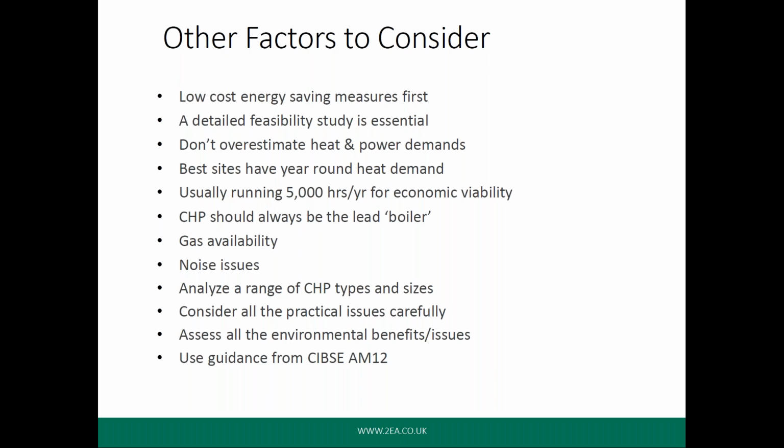Secondly, gas pressure can be an issue with combined heat and power units for a couple of reasons. The obvious one is, is there enough gas pressure on site? Unfortunately, there is not a standard pressure requirement for combined heat and power units. However, I would use a rule of thumb that under 400 to 500 kilowatt electric, 20 to 50 millibar gas pressure is okay. But above that, you will need 180, sometimes up to 300 millibar. Now, there are always exceptions to this. Certain larger engines require small volumes of gas at pressures of several bar, so always check with your chosen supplier.